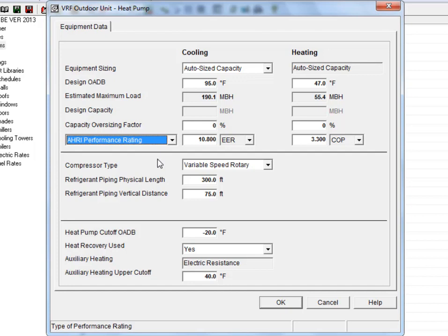During the energy simulation, if you take this option, HAP will automatically derive the compressor and outdoor fan kW from the EER formula for this rating to be maintained. It'll do that by subtracting the terminal indoor fan power value you had entered earlier.